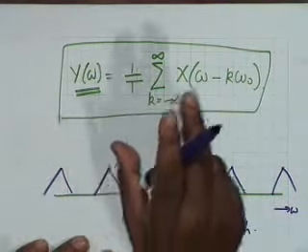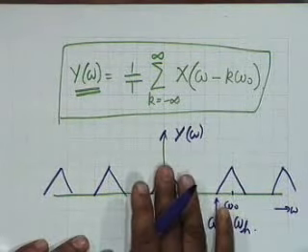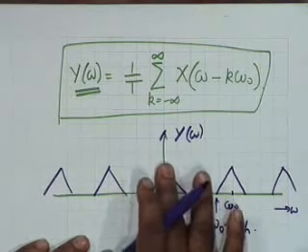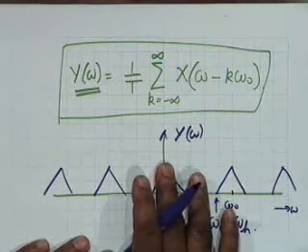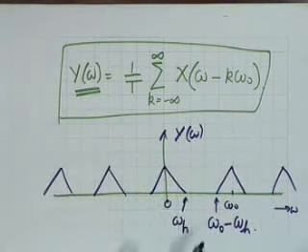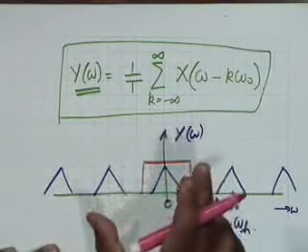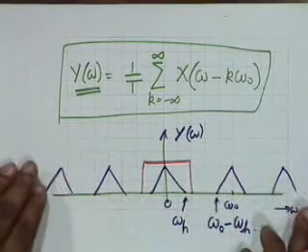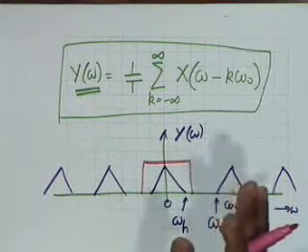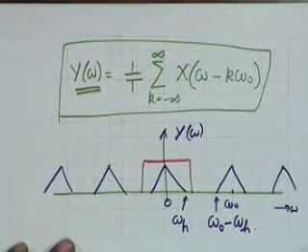All the information that is contained in the time domain is contained in the spectrum, and if I can recover this spectrum by passing through a frequency domain gate, which simply amounts to a low pass filter here, then obviously I can discard all others, and the filter, the device that I require, has to have a frequency response like this, a gate. And therefore I take the sampled signal and pass it through that frequency domain gate, all I get is this, then I take the inverse Fourier transform and I get x of t back.